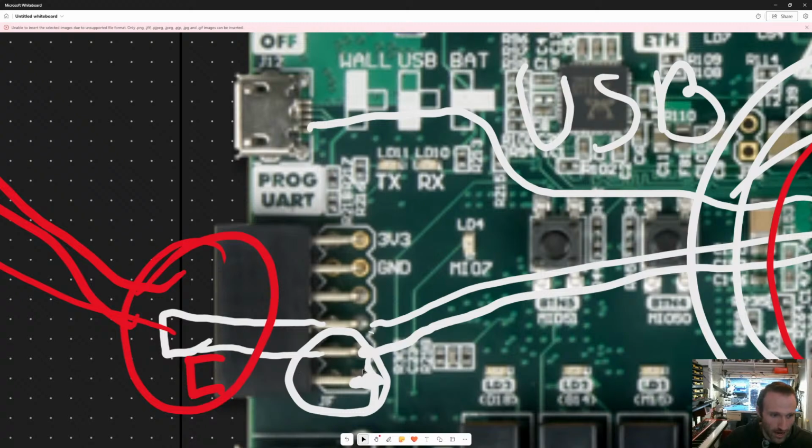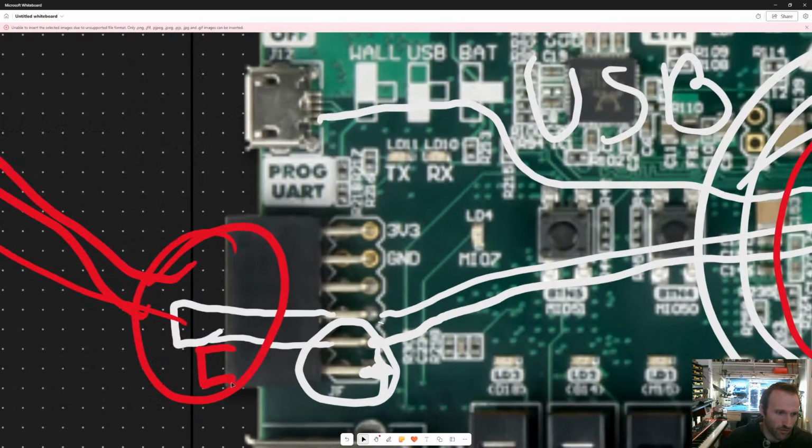When I sent out of MOSI and I tried to get that signal back, I sort of got the correct results. It was just sort of delayed. I had to do another transaction to get that data. And there's some partially incorrect bytes, but a lot of it was correct. So that's what threw me off. I was like, well, of course I have the right jumper here. I'm getting data that makes somewhat sense.